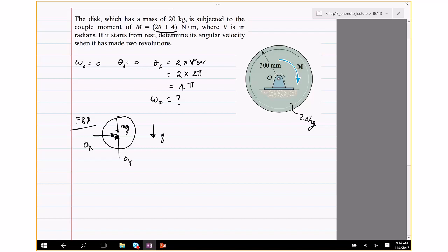Now, coming to solving it: when you see a problem like this, you can always solve problems involving forces using F equals ma. So you do not need to know anything about this chapter to solve this problem. I will write this as method 1: you can take moments about point O, since this is a case of rotation about a fixed axis, so the moment equals I_O alpha.